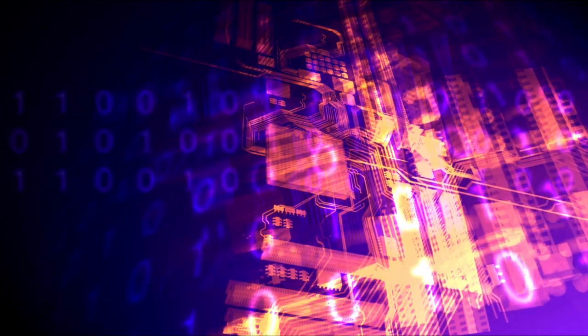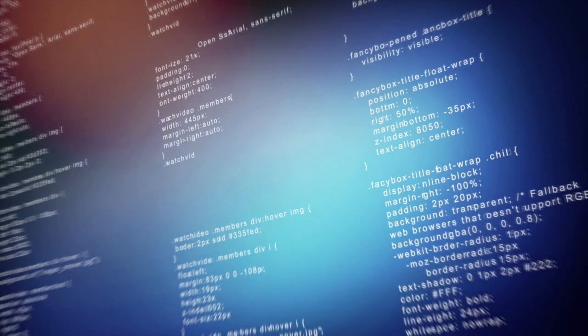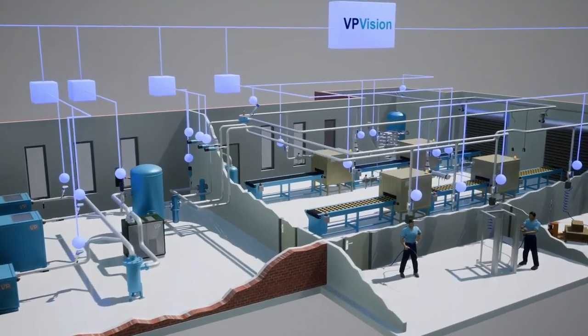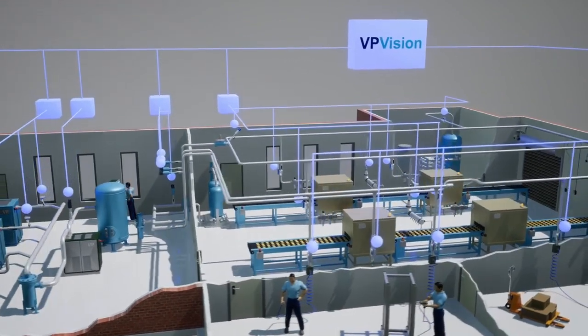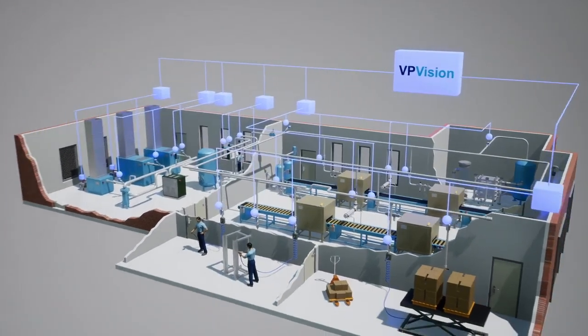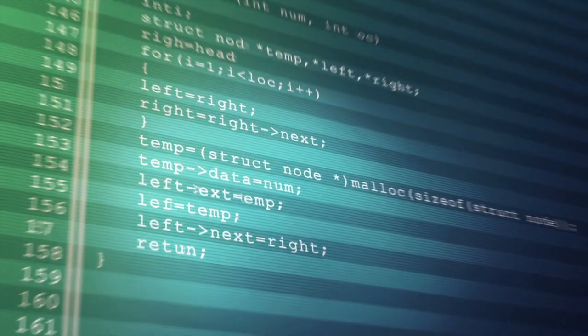Smart draining devices with data logging can tell you how often your tank is draining and give you an indication of how much water you're discharging from your compressed air system. This helps you see how well your air dryers are working and if your compressed air system is operating properly. Smart draining systems are inexpensive and easy to install, so you should recommend them to facilities even with a small number of receiver tanks. Smart devices like this are part of a group of devices that we refer to as the Internet of Things, or Industry 4.0, especially when they connect to the cloud, and are exciting developments that allow data to be uploaded directly for analysis.